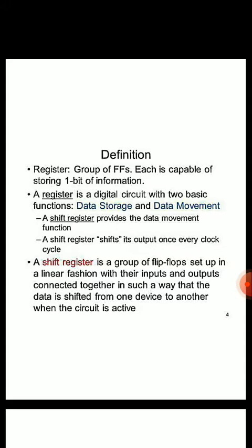Now coming to the shift register. A shift register is a group of flip-flops set in a linear fashion with their inputs and outputs connected together in such a way that the data is shifted from one device to another. Now you will ask me what is the difference between a register and a shift register. If the register is capable of shifting bits either towards the right-hand side or towards the left-hand side, then the register is known as a shift register. So a shift register is a type of register.